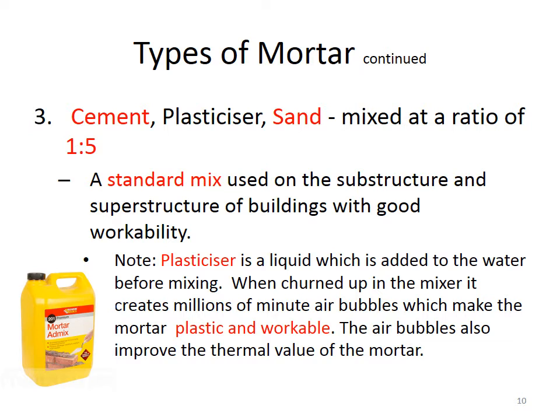So it's quite similar really to washing up liquid. It creates kind of millions of tiny little air bubbles. Although you shouldn't use washing up liquid instead of plasticizer in your mix. So don't be tempted to do that. It can weaken the mix considerably.